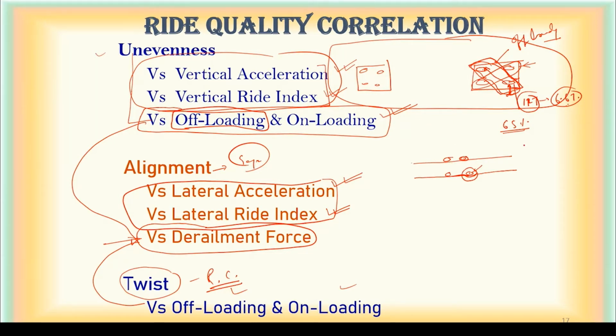And आप एक टेबल का कंसेप्ट देखिए, this is a table kept on floor. Now you cut one leg, what will happen, you cut one leg by say 1 feet, या उसके नीचे की जमीन को आप गड्ढा कर दीजिए 1 feet, क्या होगा, it will start rocking about this axis like this. ठीक है ना. Same thing will happen here, but since it is spring loaded, spring will still keep the wheels on track. अगर स्प्रिंग नहीं होता तो wheel could not have negotiated this dip, वो सीधा हैंग हो जाता.